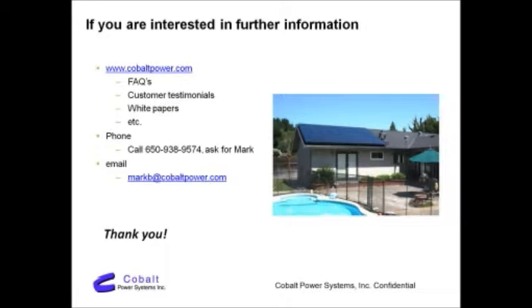Great question. So in terms of the direction of facing, south facing is the best in the northern hemisphere, where we are here, California, because it will give you full exposure morning to night. If you're going to be off of south facing, you generally want to be west when you have time of use rate schedules. And if you don't have time of use rate schedules, east and west are equivalent. So sort of the absolute pure optimum is about south by southwest, because it'll catch sun the whole day, but it'll really crank in the afternoon if you have time of use.